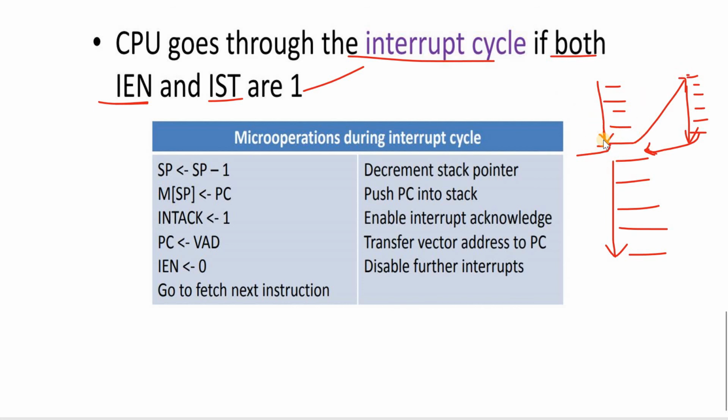So what will happen when the interrupt goes to another location? Previously the program counter was advanced and pointed to the next address location. This address is pushed onto the stack. The stack memory is temporary storage, and the stack pointer always points to the top of the stack.